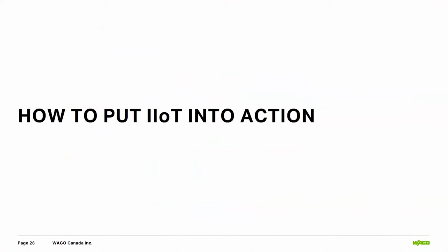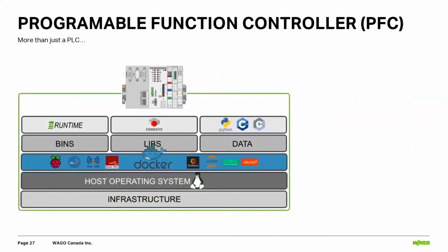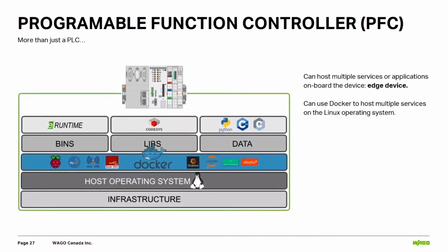So how do I put IoT into action? Just to give you an introduction to our WAGO PFCs, we actually call them programmable function controllers, not a programmable logic controller, even though I will a number of times call them a PLC. They do a lot more than just a PLC, so we like to call them a PFC. And why is that? Well, the nice thing about the WAGO PLC is it essentially is a microcontroller with an I/O system that can host a number of services. It runs a host operating system, which is Linux, and we could use a system like Docker to host multiple services right on the Linux operating system.